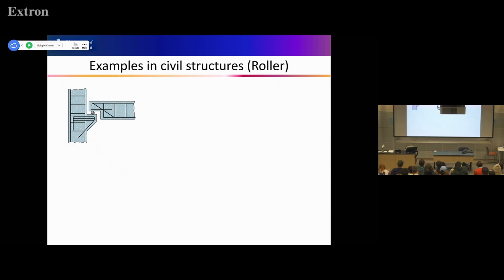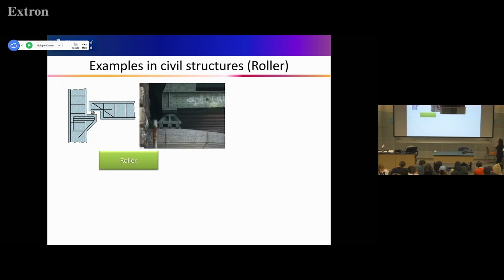And then the second in-between one is a roller support. So typically we use a circle. You can roll, right? So here's something like this. It's a roller support. And then, let's see, here, do you see this support? So here, this is connection, and these three rollers are roller support, and it can move in x direction.